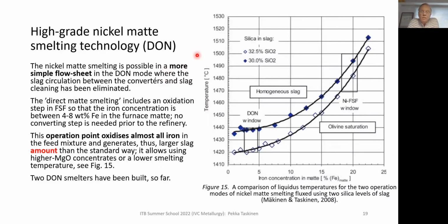What happened with the slag in general? So when we look at the melting temperature of typical traditional slags coming from the conventional flash melting process, with high MgO concentrations, those melting temperatures may be up to 1500, which is much too high for this furnace design.